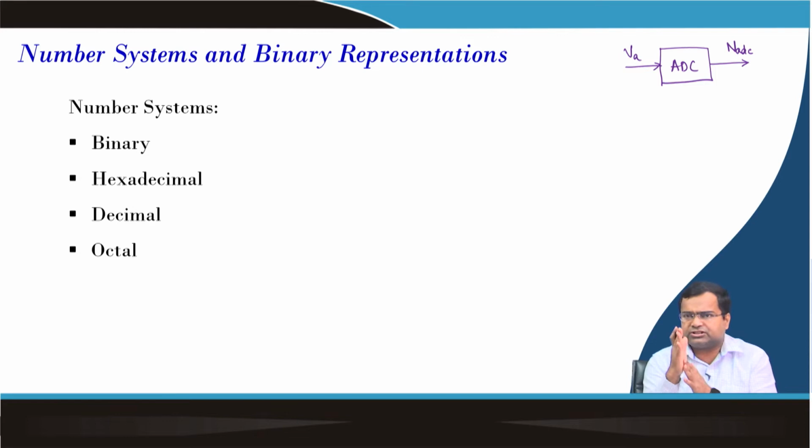So, first it will start with a start bit, then it will have MSB, LSB depending upon the type. It can be successive approximation, whatever ADC we use, but in case of a serial ADC, we need to understand the data format, whether the data comes from the MSB or LSB, then serially one by one data will come, and once the data is over, then it is the start of the next conversion. So, we should not mix the data corresponding to a particular sample with the data of the next sample. We should separate it, but as you know, a serial ADC has only one output wire or connection. So, naturally the data will come serially.